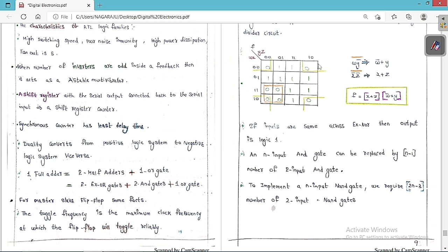So here for this one, listen carefully. If you group all these zeros, this W is one variable common, and here is one more variable common, which is Y bar. So W into Y bar. Now for this one, the common term here, 0 0, is X bar, and here the common term, 0 0 0, is W, Z bar is common. So here X bar is common and here Z bar is common. Therefore X bar, Z bar and W Y bar.